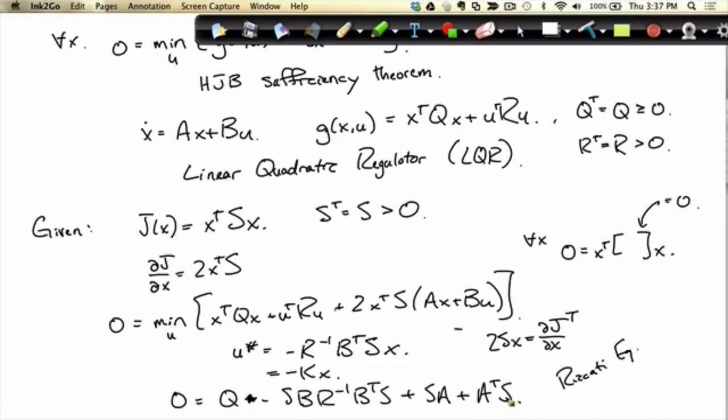You can call the algebraic Riccati equation solutions in MATLAB, or you can even just directly in MATLAB call LQR, and what you get out is K and S given LQR. You just tell it A, B, Q, and R. Okay? I find myself making this sort of very scary measure of importance. Obviously it's an important result if there's a MATLAB function that has the name, so by the MATLAB test, it's an important result, right?